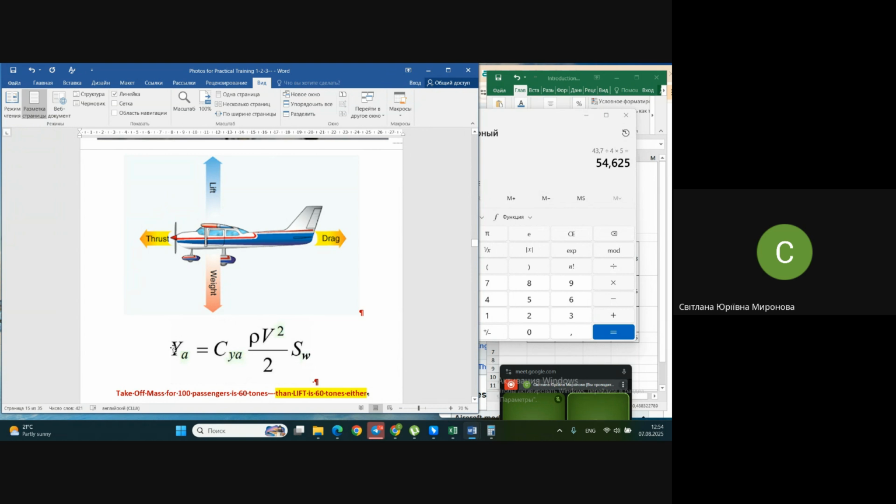Next, in cruise flight, lift equal to the weight. But in order to make airplane take off and take heights, it's necessary to have lift sometimes more. What does it mean sometimes more for you? You are not fighters, you do remember, please. So you should not take it 5 times more, 3 times more. It's too much. For passenger or cargo airplane, it will be too much. But at least something like 1.2 with respect to the normal cruise flight, or 1.3, like 30% of overload.